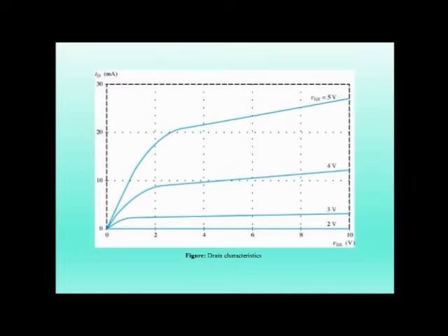This is a plot of the drain characteristics. You can see how, as VDS changes, the value of ID also changes. It reaches the saturation level, and this is mainly controlled by VGS. In the case of JFET, we apply a negative VGS, reverse bias, but in the case of MOSFET we apply a positive one because it is an E-MOSFET, enhancement type MOSFET. We first have to enhance the channel, or open up the channel, and then we can utilize it for the flow of electrons.